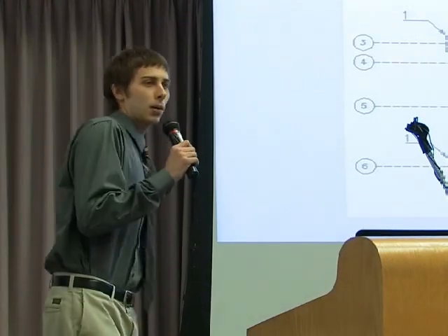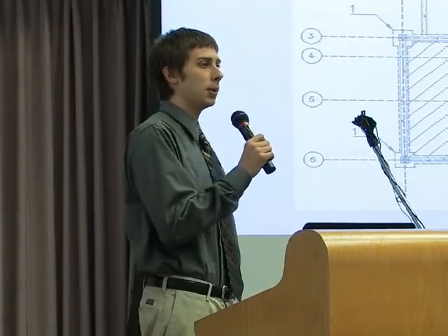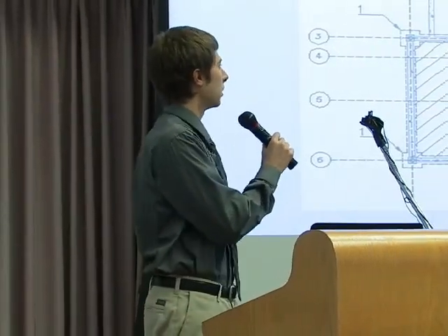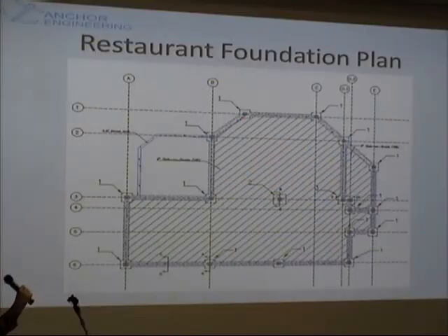All right, so we have a fairly light single-story structure, so the foundation plan is very simple. We're looking at a 4-inch thick floating slab on grade surrounded by a continuous foundation wall that thickens up around the exterior columns to form the footing for those columns. And there is an isolated square footing underneath that central column.